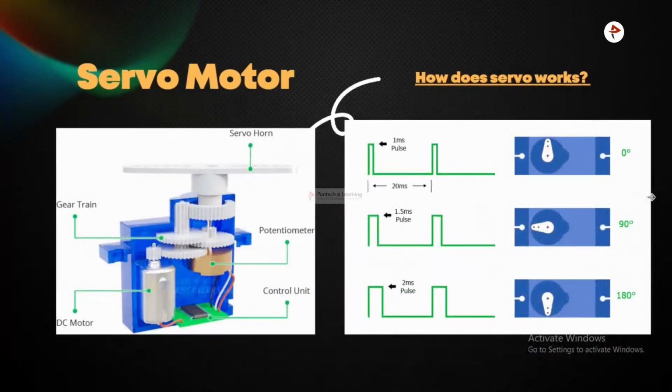Servo motor. So first, servos are motors that allow you to precisely control physical movement because they generally move to a position rather than continuously rotating. They are simple to connect and control because the motor driver is built right into them. So, the servo contains a small DC motor connected to the output shaft through gears.